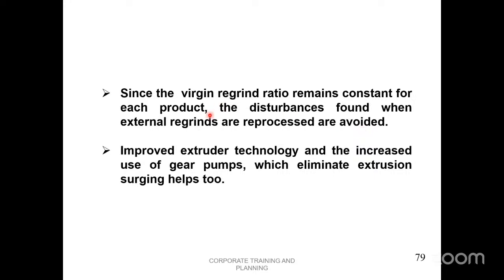Now, improved extruder technology and the increased use of gear pumps, which eliminate extrusion surging, help too. Yes. See, if there is a constant flow in the extruder barrel, then we are using the gear pumps. Secondly, if the material has a very high viscosity, at such a time you have to use the gear pumps there to push the material constantly.